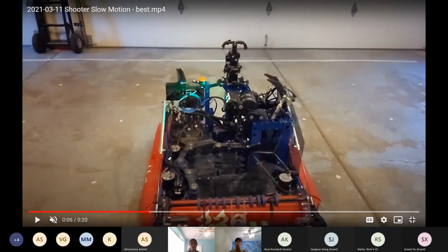You see how they travel through the robot and then go up using this belt and pulley system. Because the hood angle is set to this degree, it will go at a higher arc. If it was set to a lower degree, it would go a little bit more horizontally. So if you guys go that again.